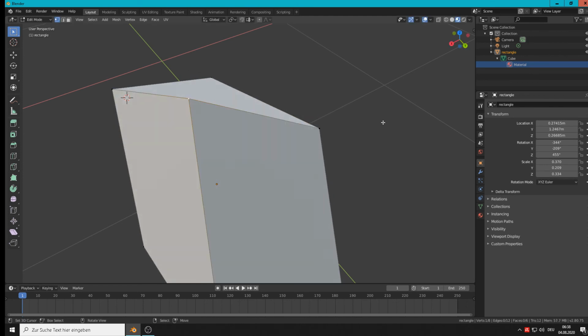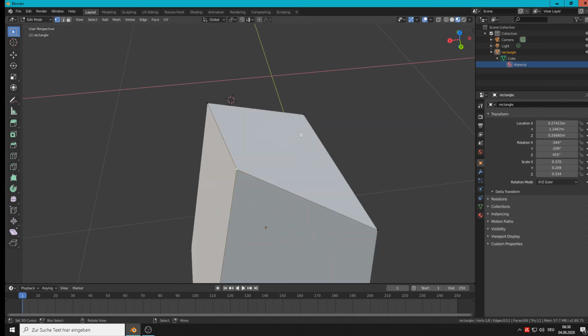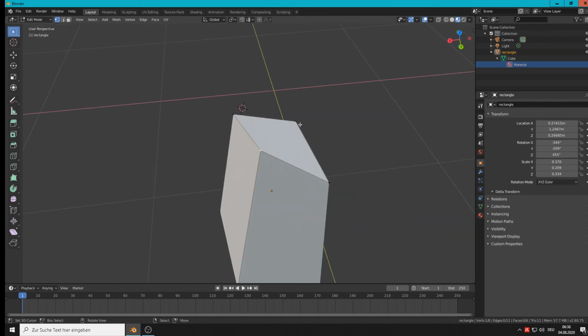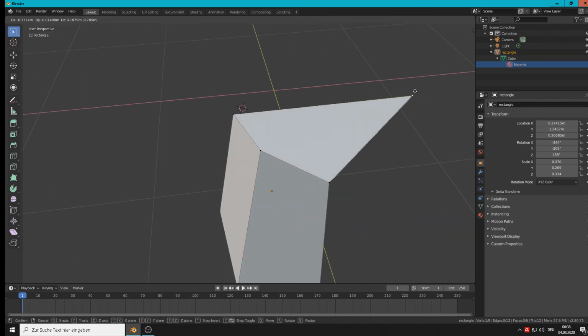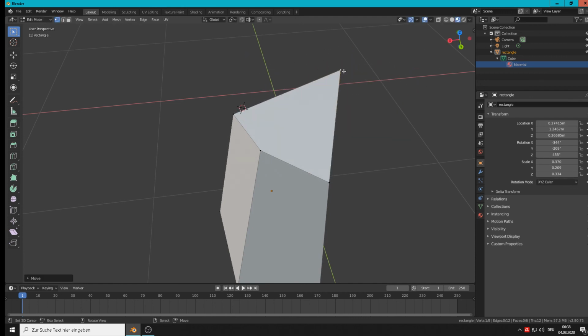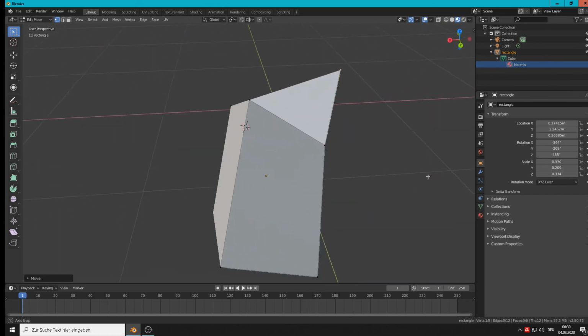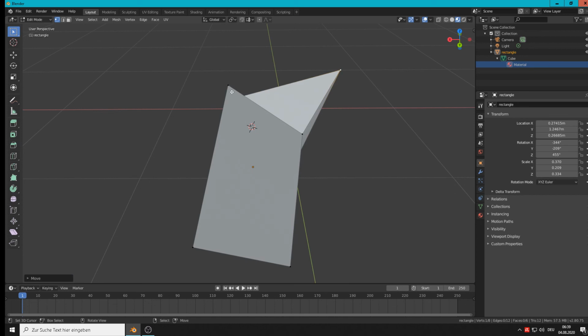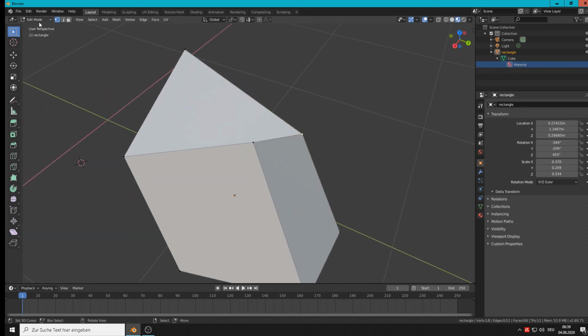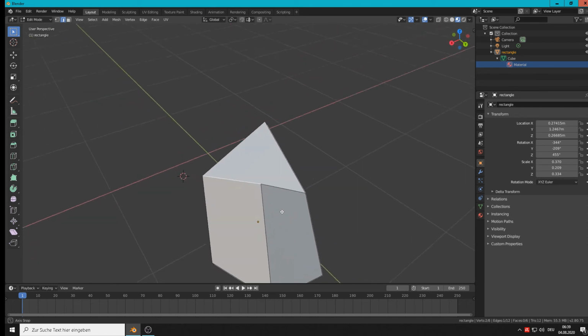And to accept the movement, the grabbing, you press G and move them where you want, and then left click to accept the position there. Good. Those are vertices. Vertices are the points, and they are only visible in the edit mode, not in the object mode. Then we have here edge selection. An edge is this here.